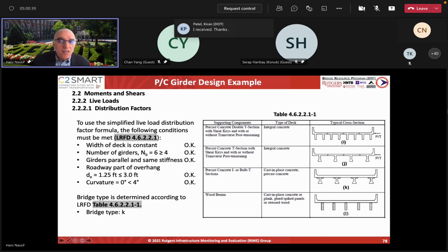However, for shear, if you're doing it at one of the supports, you might have to use the spacing at the ends rather than in the middle. To get a factual number, you might go with the most conservative, but that would sometimes be too conservative an estimate. So for shear, I would use the girder spacing where you are placing the truck, because the distribution follows the transverse location where the moment or the shear is being considered.